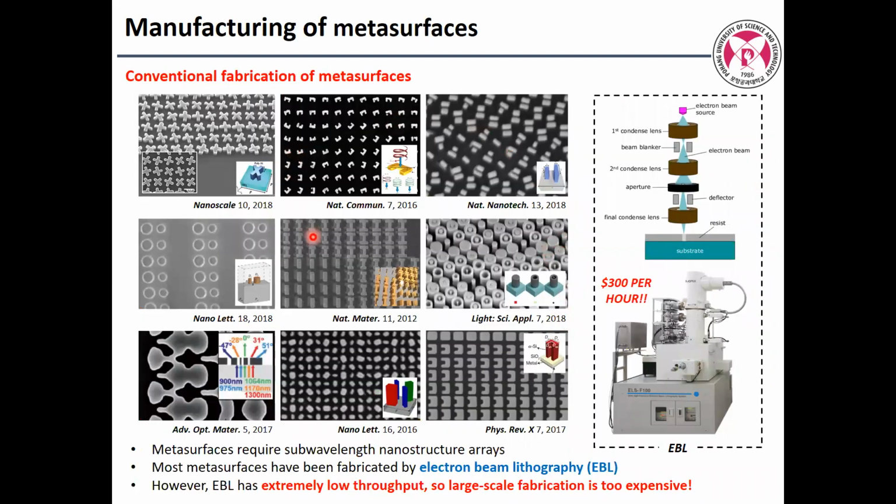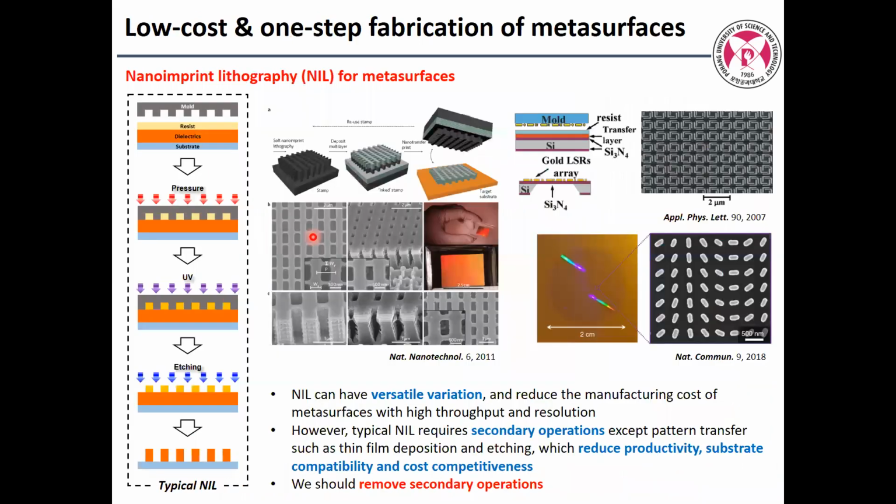Yeah, the main reason is that lithography, e-beam lithography, is expensive. So people in general propose an imprinting method. It's a very easy way to consider. But in typical nano imprinting, you can see the substrate, functional layer, resist, and molding, and then we have a sacrificial layer, and you need to do etching or deposition, like a second step process. So this is an example by modulus printing or nano imprinting making a centimeter scale metal lens array.